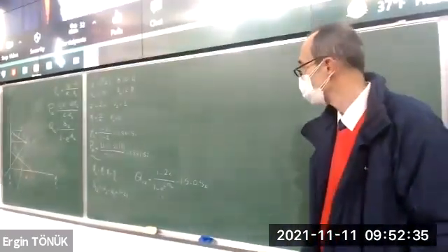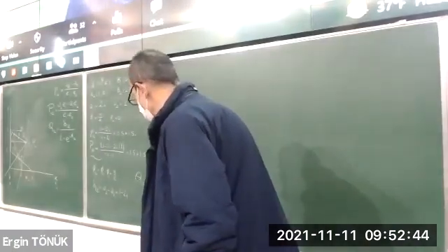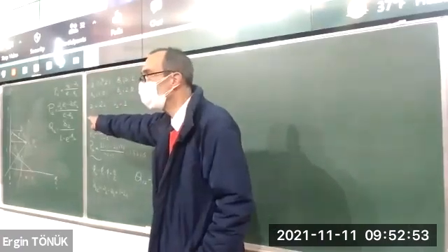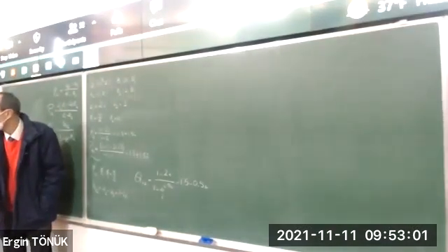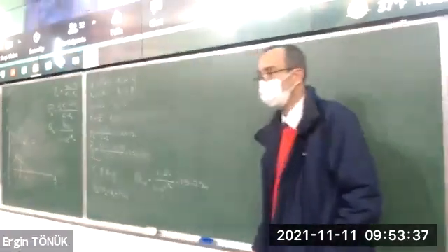Any questions on this? This equation or how I draw it? Which both? This or that? That one. Okay. Now, Q is a vector that points from A1 to the pole. Am I right? So, I start from A1, I travel 1.5 and negative 0.5. And then I find the pole. Okay, so it's a vector from A1 to the pole. That's it. In the absolute coordinates. But it's independent of the origin. It's relative to A1. Okay? Good. Any other questions?